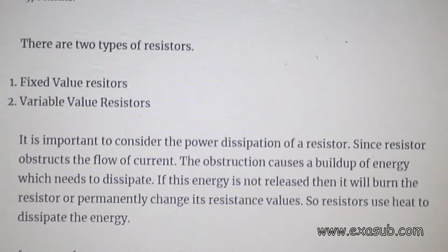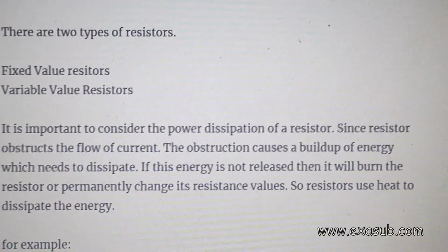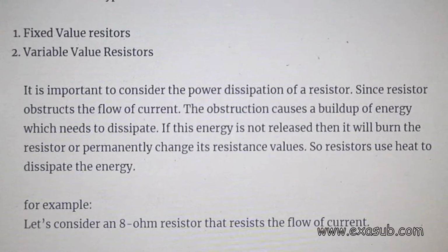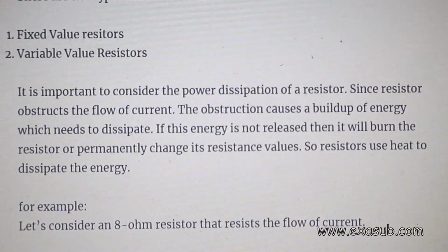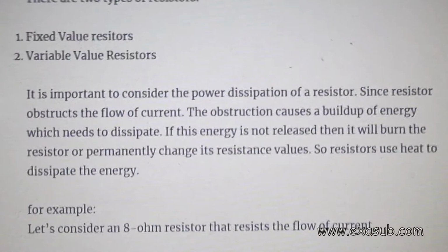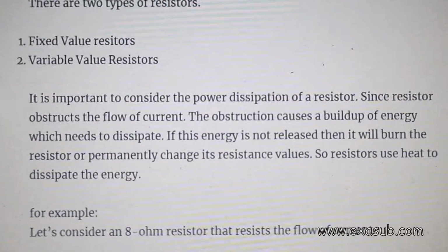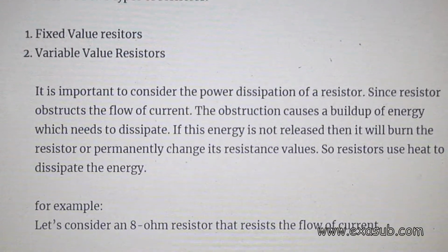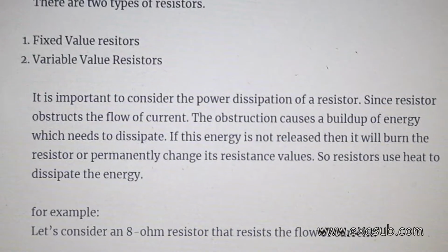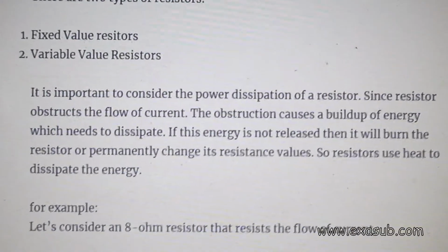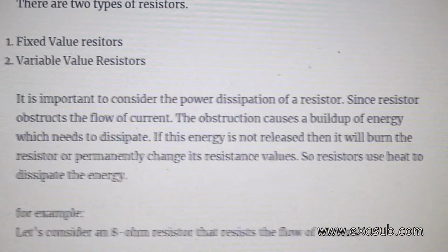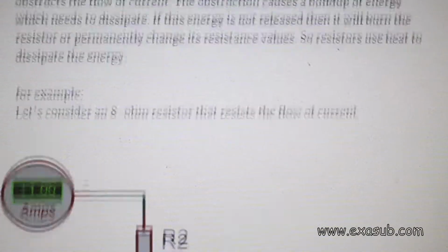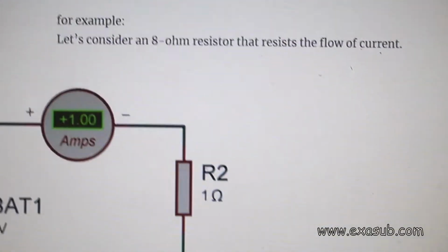It is important to consider the power dissipation of a resistor. Since a resistor obstructs the flow of current, the obstruction causes a buildup of energy which needs to dissipate. If this energy is not released, then it will burn the resistor or permanently change its resistance value. So resistors use heat to dissipate the energy.